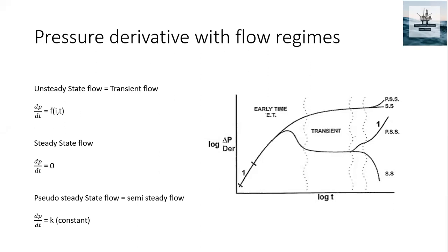The same way, a pressure ripple will be generated near the wellbore where the perforations have been made. So once you open the perforations, a pressure ripple will be generated. That is, pressure ripple means reduction of pressure starts near the perforations once you start producing crude oil.